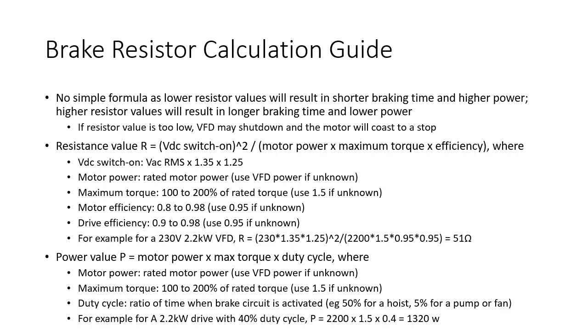You've got to be careful. If the resistor value is too low, that could effectively cause a short circuit on the VFD, and that could cause the VFD to stop, and then the motor will just coast to a stop. So if your resistor value is very low, that's an issue. But you can do some calculations based on these formulas we've got here. There are two parameters of a resistor you need to calculate: the resistance value and the power value.